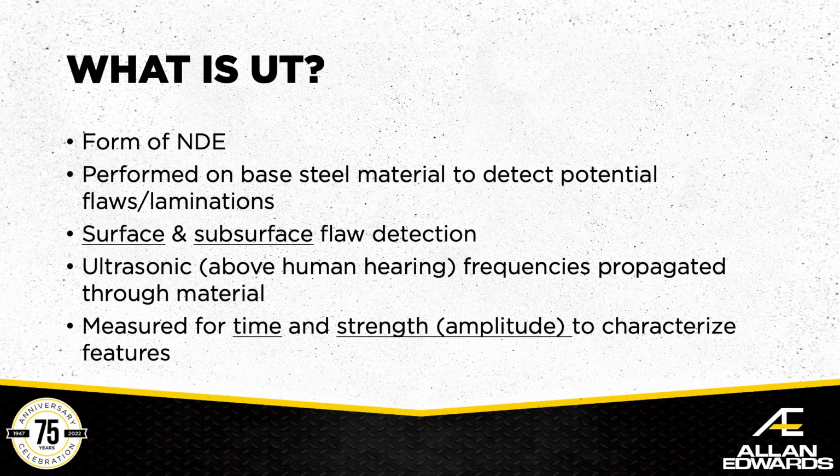So it can detect surface and subsurface flaws, and it allows for that ultrasonic frequency propagating through the material, right? So you have some sort of transducer, and it kicks in, and it measures some sort of time and strength to get the feature or get the ultrasonic sound back out. Interpretation of that is done by some software package or someone that's an expert in the field, who can then help characterize what exactly that feature is. You're seeing some dip, some change in time, and then you're able to interpret that as, oh, it looks like wall loss, or it looks like a lamination, something thereof.